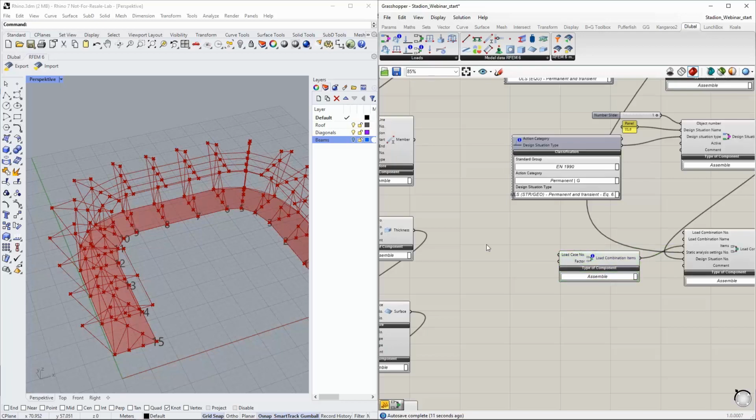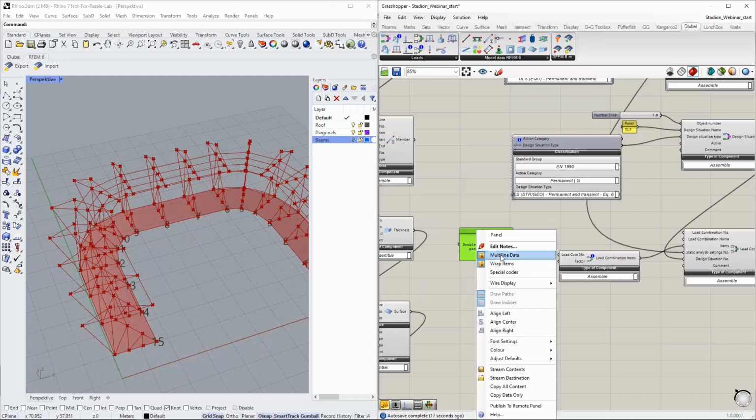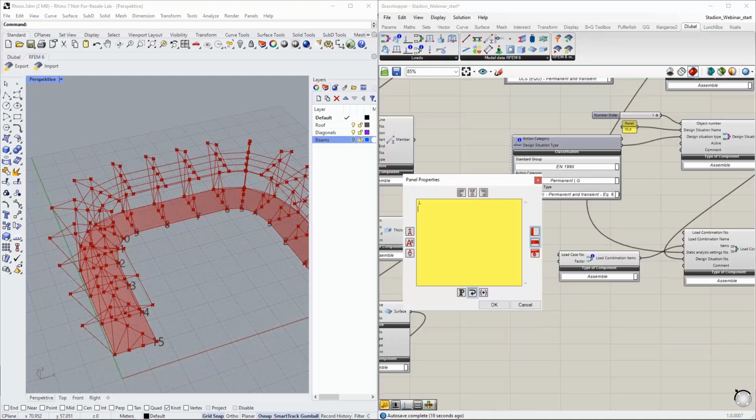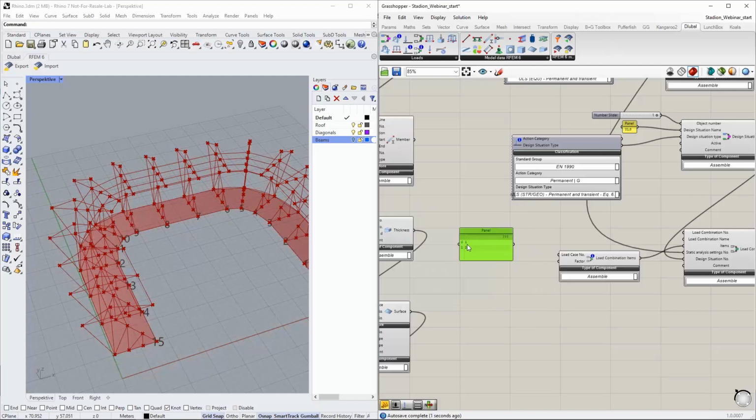And to define a load combination, we have to follow these rules. We have to create, for example, a small list. And in that list, I can say, okay, I want to combine load case 1 and load case 2. Let's say I would like to have a load combination with the factor 1.35 for the dead loads plus 1.5 for the live loads or imposed loads.